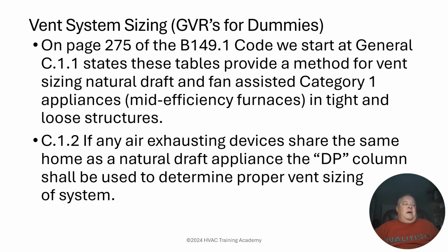So keep in mind, when you look at a TSSA fuel safety exam, they would have to tell you in that case that there are air exhausting appliances in that house to make you use the DP column. If there is no mention of air exhausting appliances, then you won't use the DP column. You'll use what we call the max column, okay? In the field,